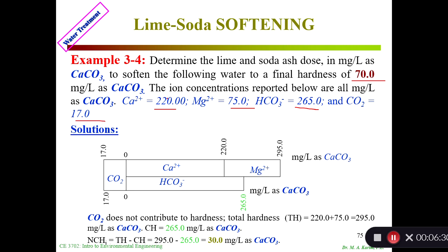By the way, these are the parameters we can measure in water in the lab. We have turbidity and hardness meters in the lab, so we should be able to calculate those. And using the atomic absorption spectrophotometer, we should be able to find the calcium, magnesium, and other things like that.